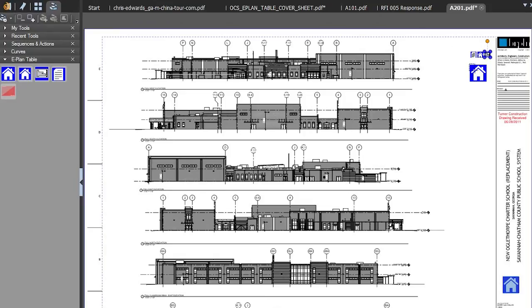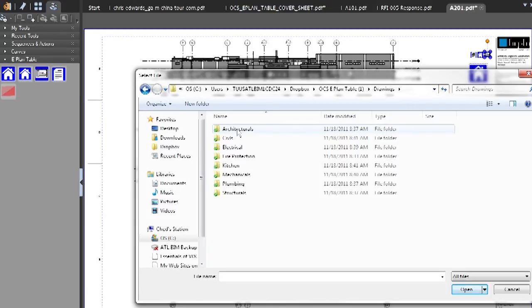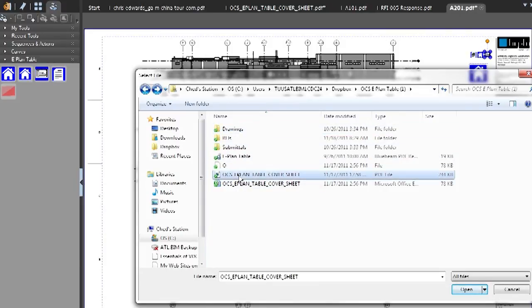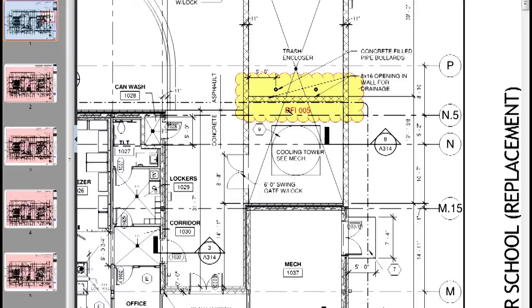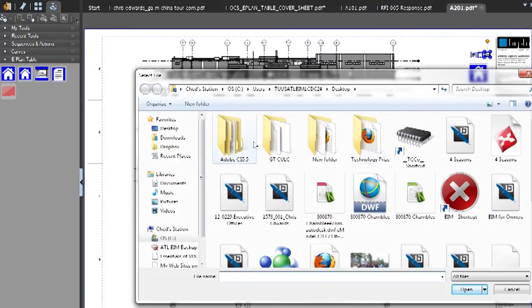After that, we can go in and hyperlink these, and you simply click on the hyperlink, select where you want to open that file from, and make sure you check the button for Use Relative Paths. This is going to allow you to translate this to different computers, and it's not going to have to remember exactly where this file was on your specific computer. And once you've completed all your hyperlinks, now you can navigate around the documents with ease.